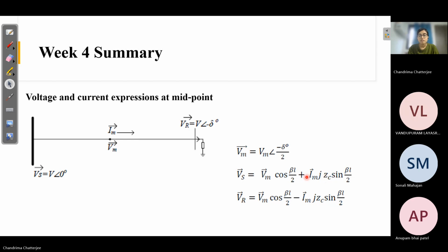After you just substitute all these values, for now one thing you will have to remember, that whatever discussion we are doing here, we are always assuming that the line is symmetrical, lossless. Okay, that you will have to remember. For lossless line, there is only reactive part, there is only reactance in the transmission line, there is no resistive part. So obviously the active power will be same throughout the transmission line, as we already discussed in the earlier session. And another thing is symmetrical.